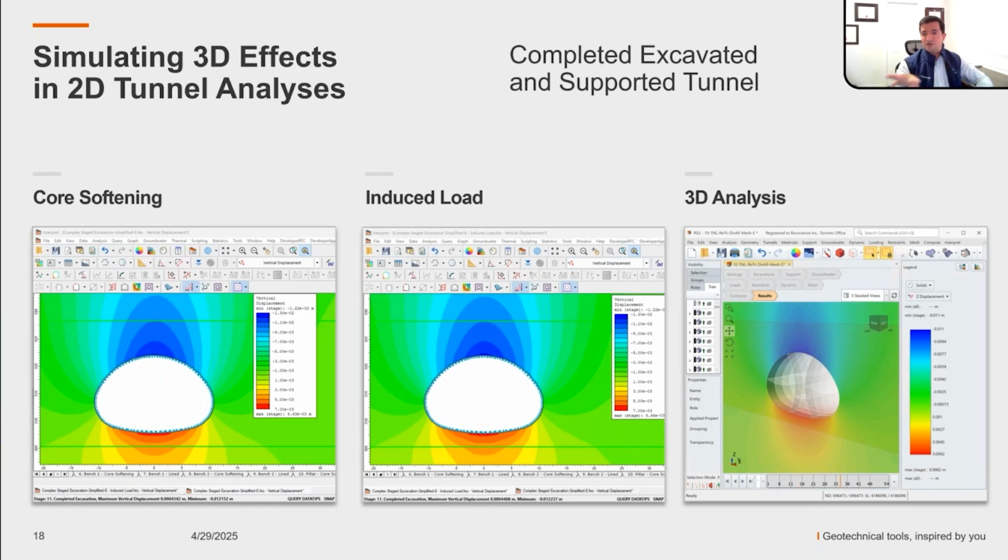As you saw between all these 3 scenarios that I'm showing you, the pattern, the values, and all that are very much in agreement. So for these kinds of scenarios, you can actually effectively simulate that 3D effect in 2D analysis.